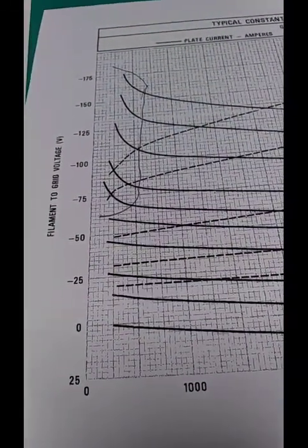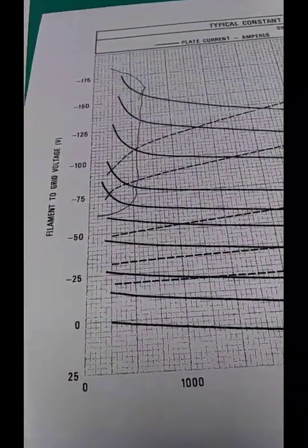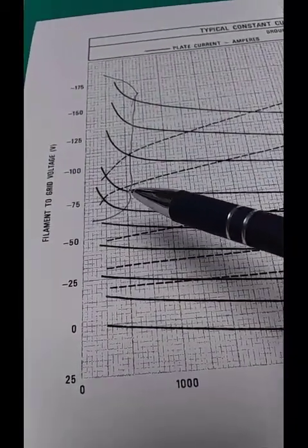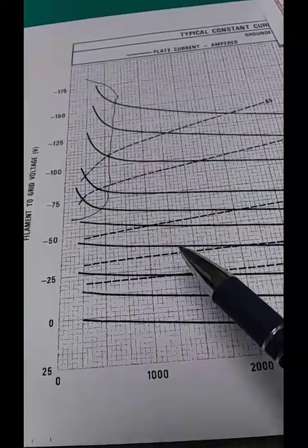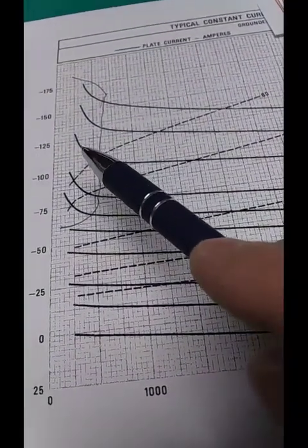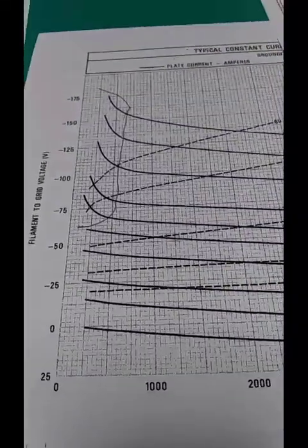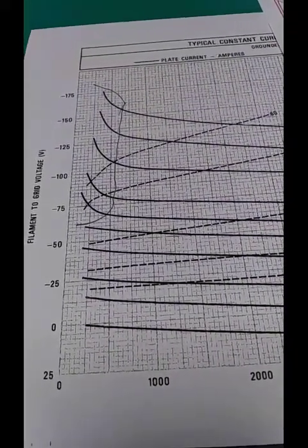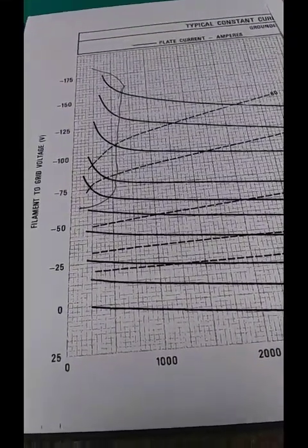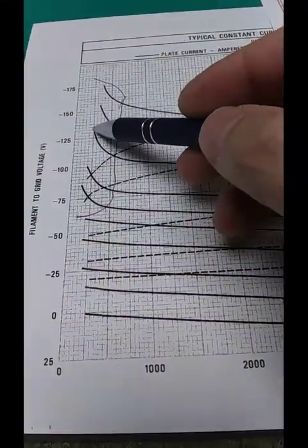It's fairly obvious that correlates with a maximum grid voltage, because if the grid voltage goes too high, which means too much drive, that line going up and to the left is going to end up in this distorted region. And that's exactly what happens and causes distortion when an operator puts too much input power to an amp and it splatters. This is the splatter zone.